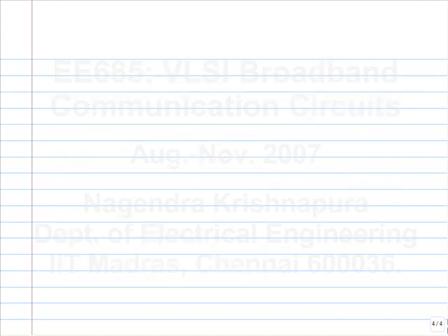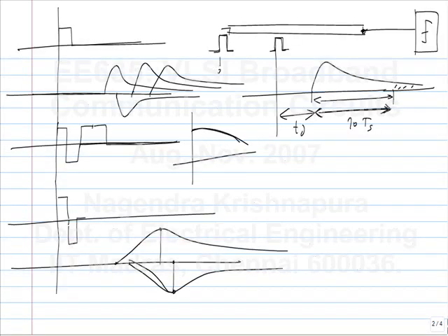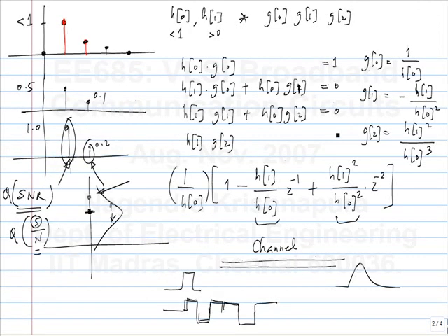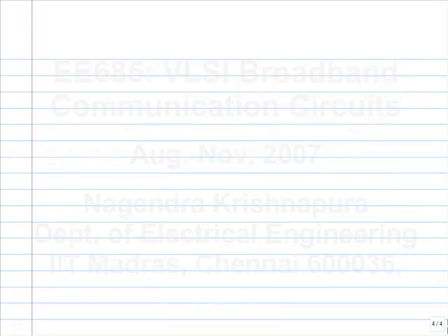Okay, any questions on the equalization and how we chose the taps, etc.? Is that the best? Did you try out something else? We had a certain way of choosing the taps, which was to make the intermediate ones 0. Whatever we can make 0, we make 0. Is that the best that we can do? Will it give you better results? So you are saying that we will minimize the powers in those other taps.